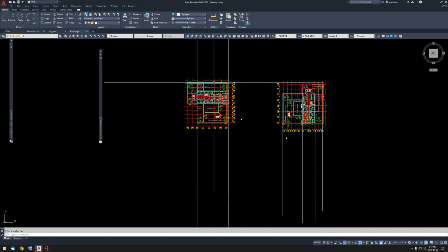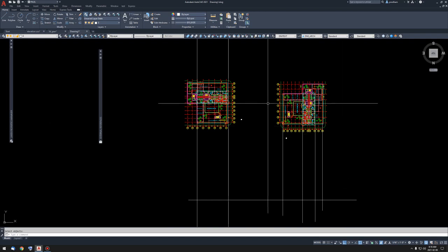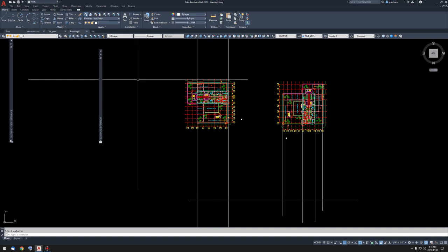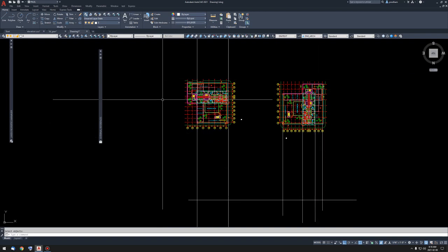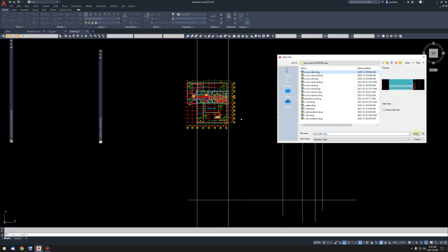If you detach these or erase them or whatever, you're going to lose a significant amount of marks, because you're not using XREFs, or I can't see that you're using XREFs in the manner that I asked you to show me. Every year people end up doing that, and it's absolutely baffling to me. So you've been told in a video to maintain this orthographic relationship between plan and elevation in your final submission drawings. Maybe the thing to do now is for me to go to the finished drawing and show you a little bit more about what makes these elevations a little bit special.